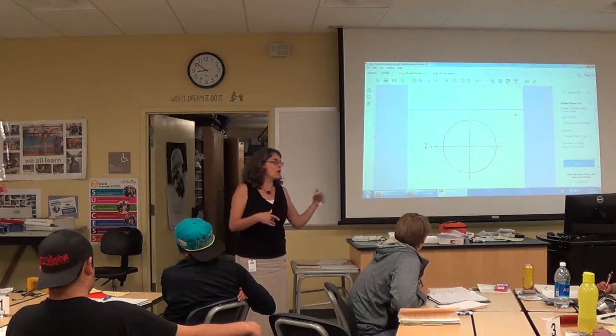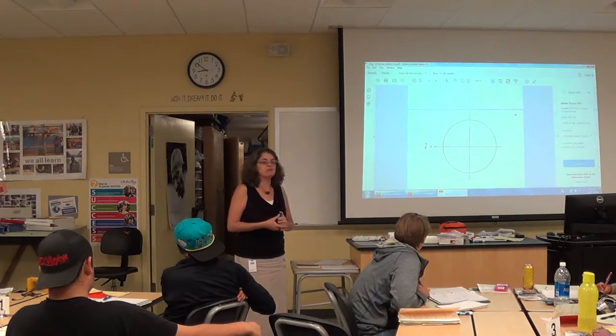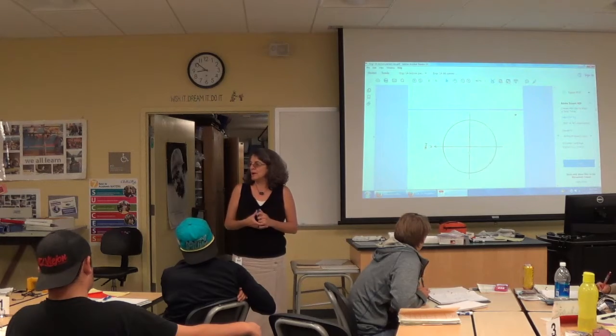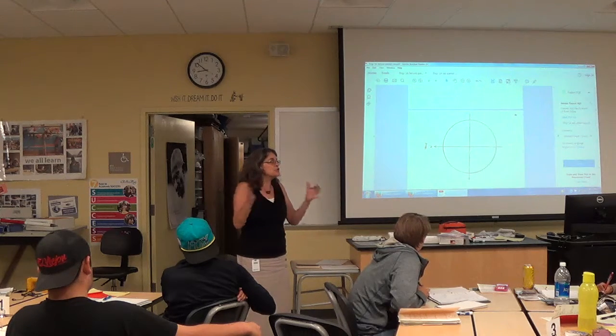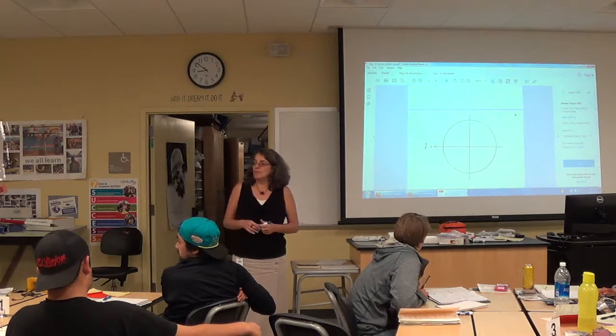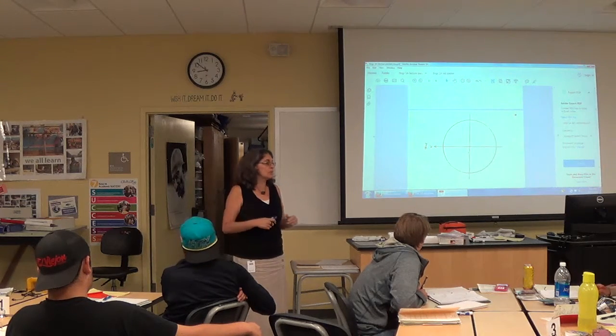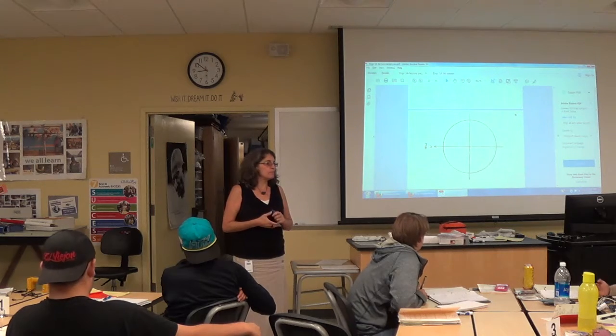You measured all the angles and you added them up and it came to 178 degrees. What's your error? 2 degrees. How did you distribute the error? You divided it by 3. It was evenly distributed. Okay.